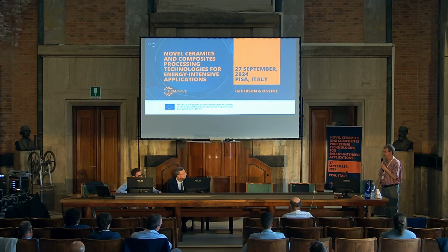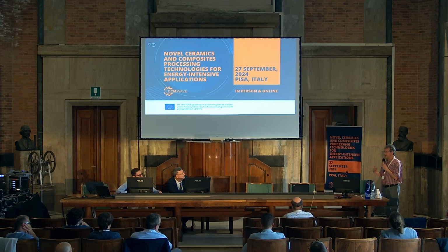In bulk ceramic samples, that is the standard way of doing toughness measurements. On filament-based structures, I'm not sure it will be meaningful because you have the interface between the filaments that act as a weak point. So in theory, I guess you should do a notch that is larger than the filament, but you would still have within the notch the interfaces. So maybe.